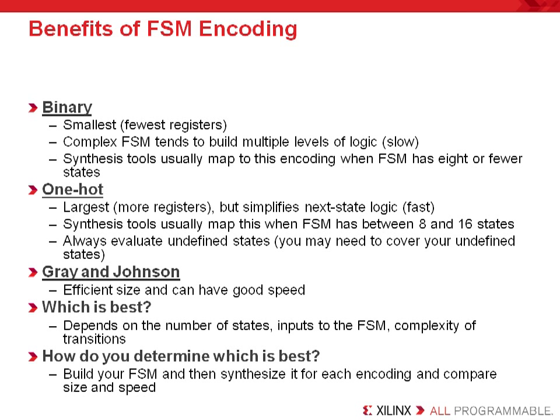Bottom line, the more complex your state machine, the more you'll benefit by trying all 3 of these different encoding techniques and comparing the size and speed of each. Don't expect your synthesis tool to do that kind of work. It's just too much for you to expect. You'll have to try this and experiment yourself.